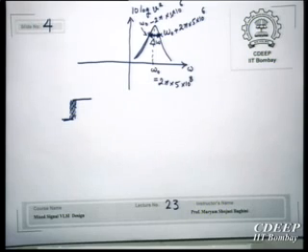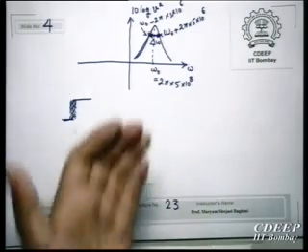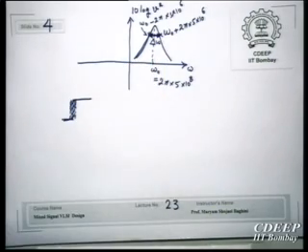Therefore, the bandwidth of the DLL will determine how much jitter will come into the DLL from the input signal, the input clock, for example. That's why less bandwidth would be better.